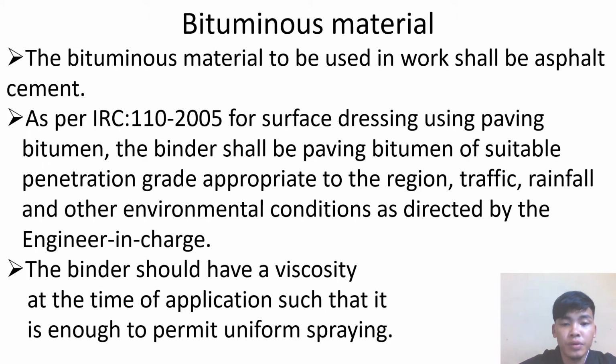The binder shall be paving bitumen of suitable penetration grade appropriate to region, traffic, rainfall, and other environmental conditions as directed by engineer in charge. The binder should be of viscosity at the time of application such that it is enough to permit uniform spraying.